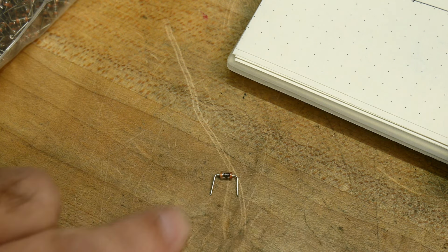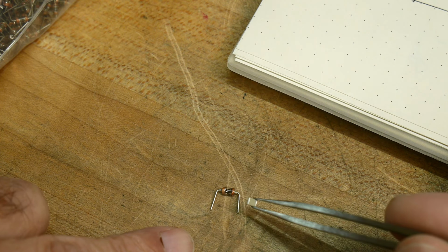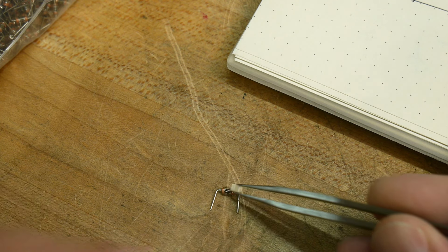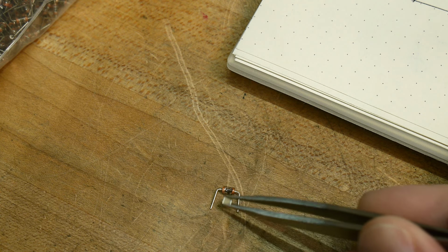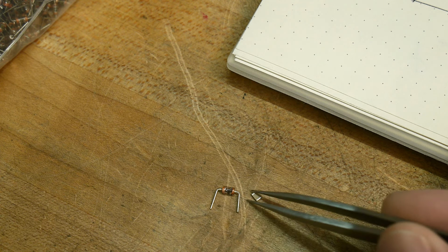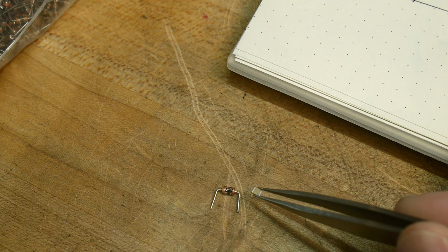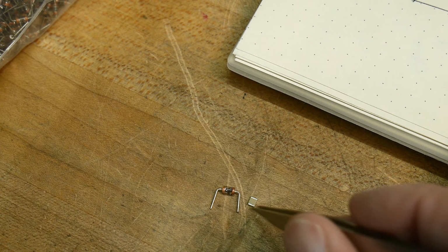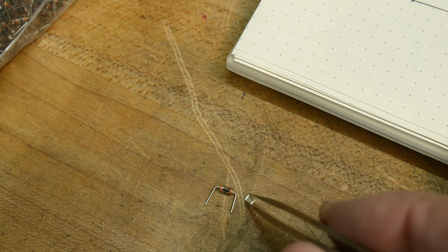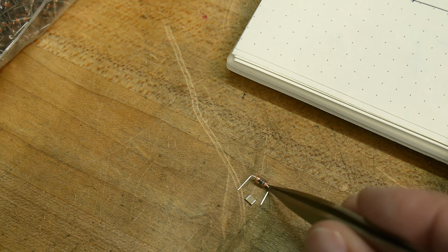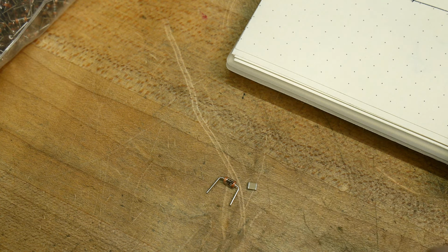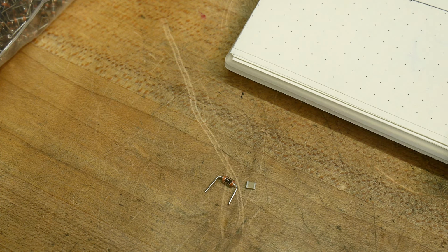Well, what if we get rid of all the leads and we just use one of these SMD parts? These are exactly the same part electrically. They're both specified as 0.1 microfarads, 50 volts, and they're Z5U. I think they're both exactly the same specifications. It's just that this one is a 1206 package, I think. Maybe it's a 1210 package. Anyway, I'm going to take our little fixture and measure this, and then I will solder in this one and measure it, and we'll see if there's a big difference between those two or not.